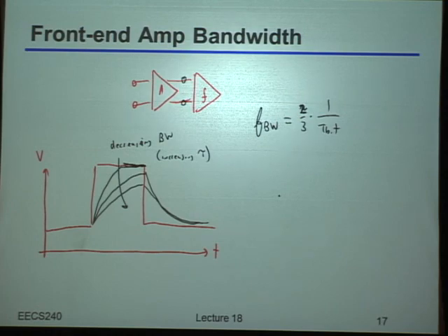So this is interesting, because now I want to ask you guys something. What is the bandwidth of a 6 gigabit per second signal? It's half. Why is it half? Yeah, okay, so you said it's Nyquist. What's the super intuitive way of thinking about it? What's the fastest changing thing you can do with a 6 gigabit per second signal?